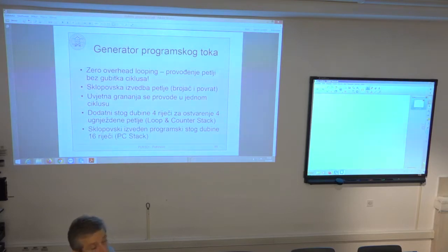Okay? And of course, once you exceed these 16 values, you cannot go further, because it cannot write the 17th value in this stack, because it is limited. In this case, you have to perform some kind of instruction-based memory stack implementation to store the 17th value in the memory, and then it is less efficient, but nevertheless, these internal levels of the nested loop are very fast, because they take the return value directly from this hardware stack without any fetching from the memory.